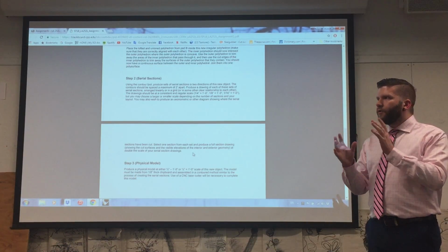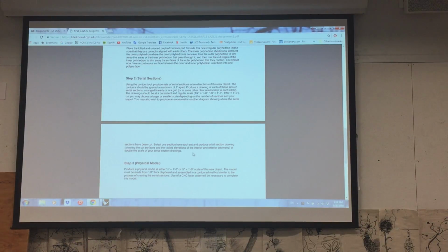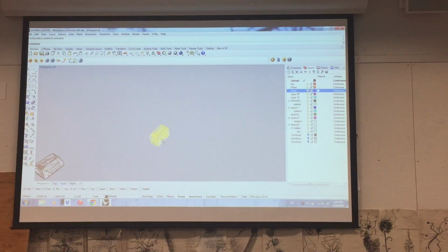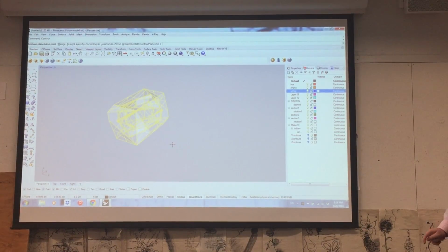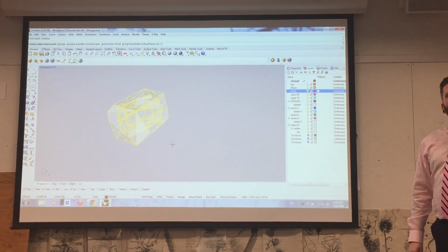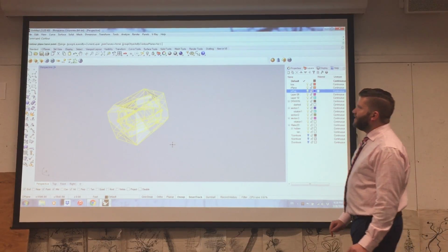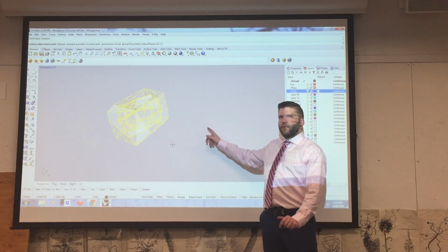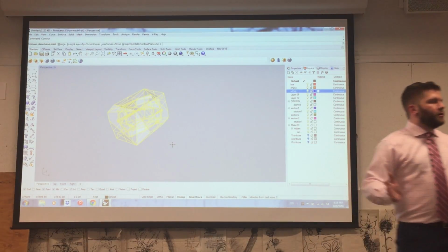I'll show you how easy this actually is. So I will take our newly created continuous surface, and I'm going to use the contour command. Right? And now what the contour command asks for is a start point and an end point of the contour vector.